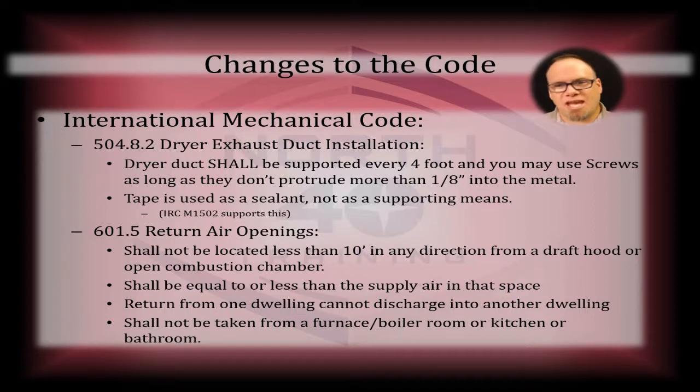If you're using tape around a joint of duct so that it doesn't pull apart or sag over time, that's support. That's not sealing. If you're putting a piece of tape around a 90 joint so it doesn't swivel, so it stays in place, that's also support.